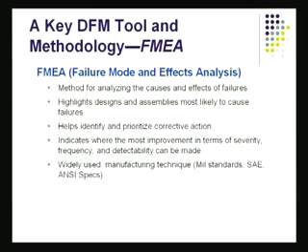Then, of course, you move slowly into FMEA. FMEA is really failure mode and effect analysis. What is this approach? You try to predict failures, and you try to look at, first of all, the different modes by which it can fail. What are the different ways a disk drive could fail, for example? Then you try to identify what would be the impact if that particular thing failed, and what is the likelihood for it.